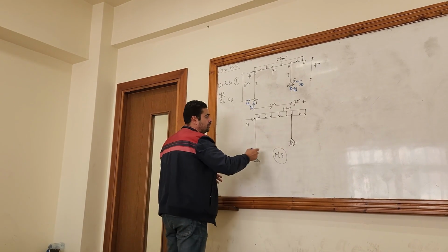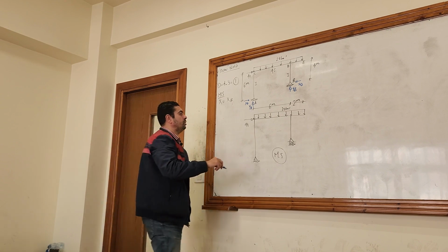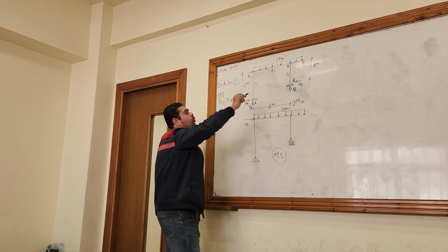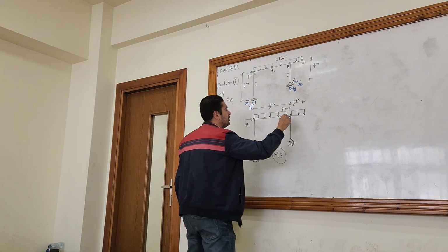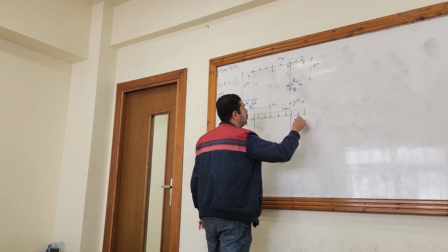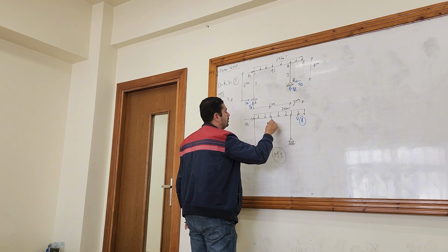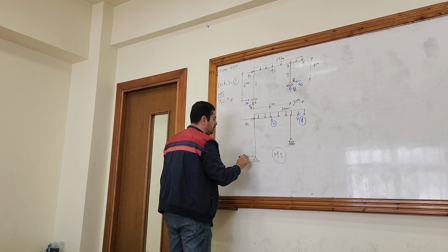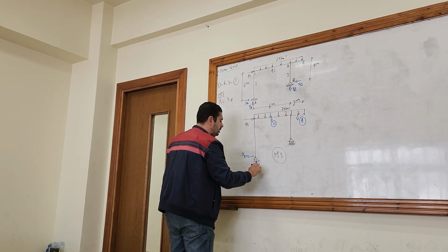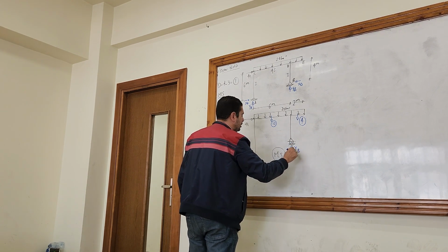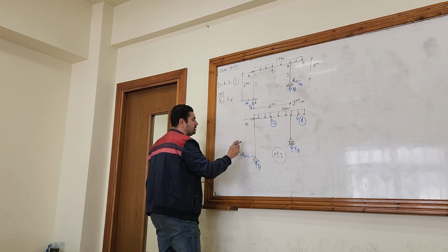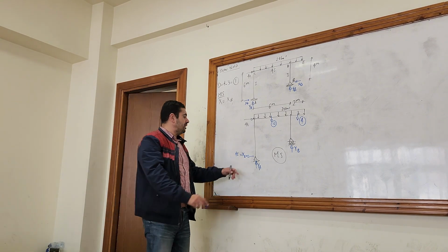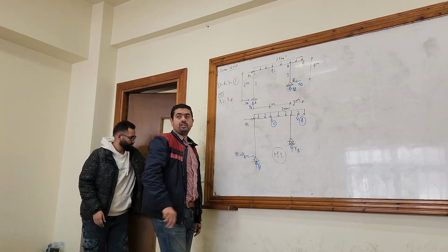Okay, so in order to calculate the reactions here, I first have to concentrate the uniform distributed load. It is on 2 members, CD and DE. So I have to concentrate this first: 2 times 2, 4, and 2 times 6, 12. I have here XA and YA, and here I have YB. XA directly will be equal to 4 tons, in the opposite direction of the horizontal force at C. So XA equals 4.